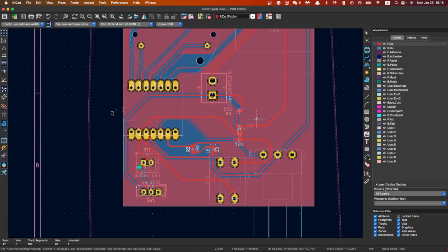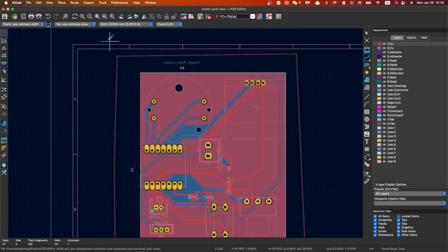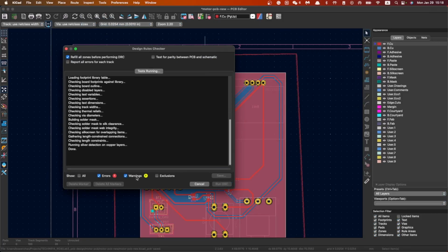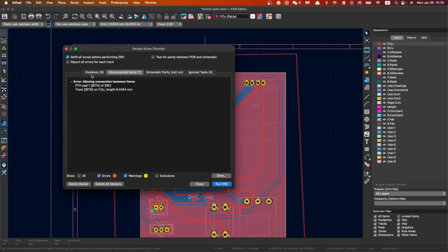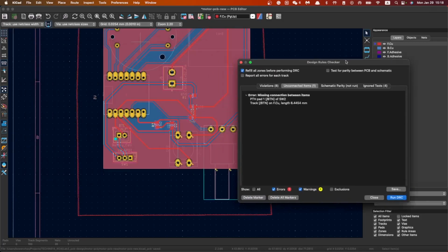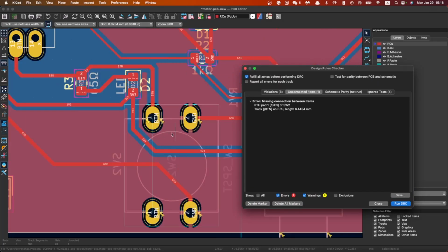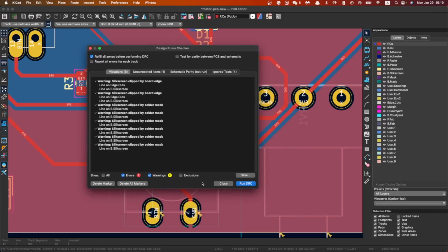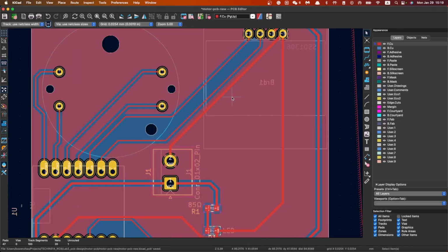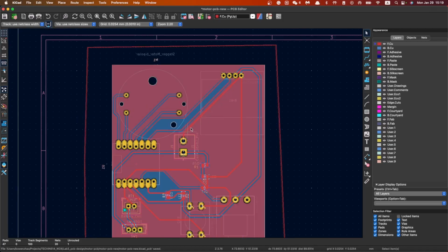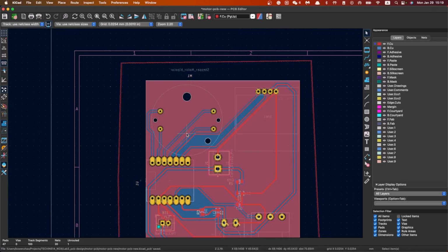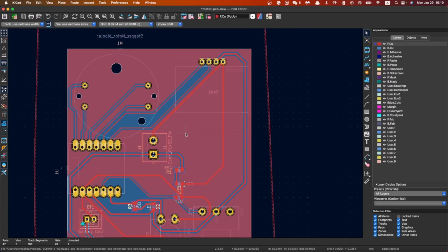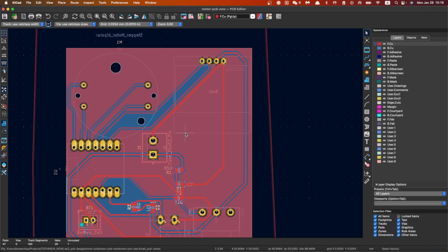And the last step is, of course, do the DRC checker again. Run it. One error was this error, unconnected item, because we are not connecting the pads between these buttons. Remember, so there's no need to worry about that. And boom. Yes. And now, as you can see, the ground plane has been updated, and it looks perfect. I would say I like this one better. I'll just click save, and this will be my new PCB board to be printed out.